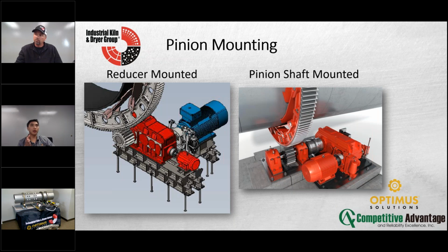But also, because it's higher precision, you don't have as much play to, say, move the unit uphill, downhill, because you want to keep that gear in the gearbox. And so this is where later we'll talk a little bit about the thrust roller and making sure it's tight. If you got a chain system, chain systems are a little bit cheaper. It's sloppier in the sense it's chain, right? Right. You can move back and forth a little bit. The issue is then you may be replacing chain more, et cetera, et cetera.